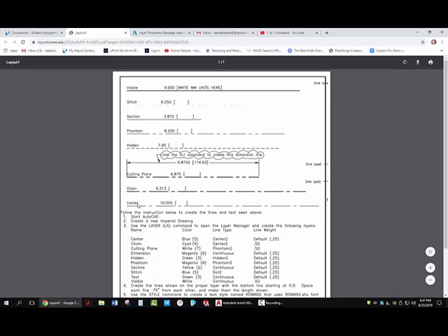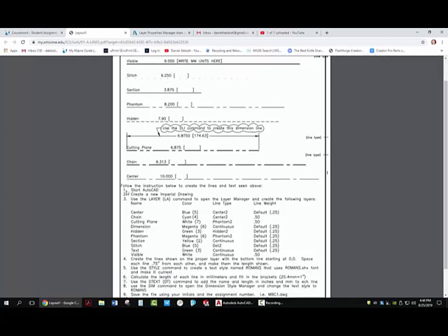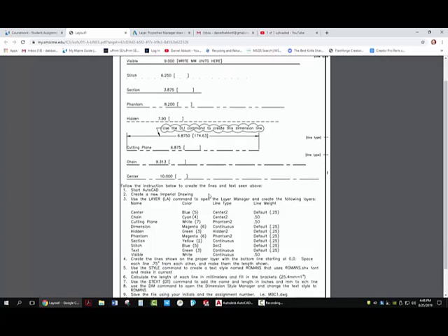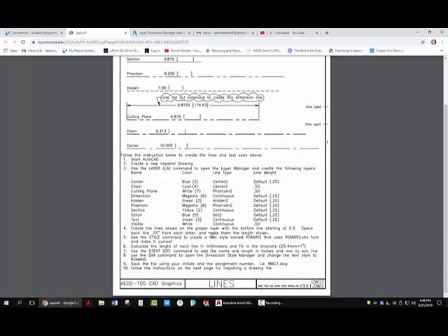The idea is to use layers to control both the line type and line weight, and also to recognize what these line types mean. This is a two-part assignment. This is the first part. The instructions below say start AutoCAD, create a new imperial drawing, which would be done with the acad.dwt template, and then to use the layer command to create these layers. Once you've done that, you're going to draw each of these lines and place each line on the proper layer, and then label those lines. All you have to do is just follow the instructions, and then you'll be able to do that.